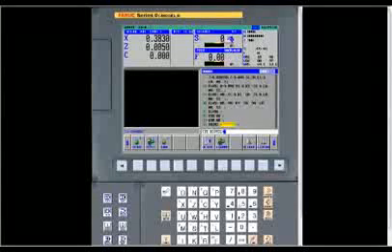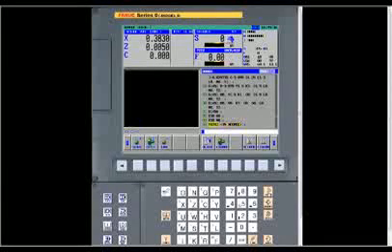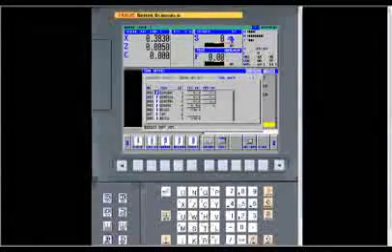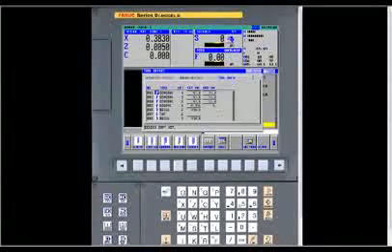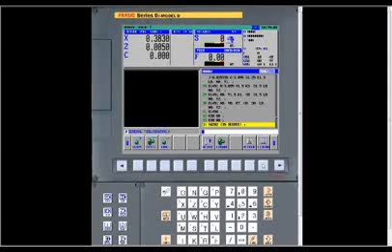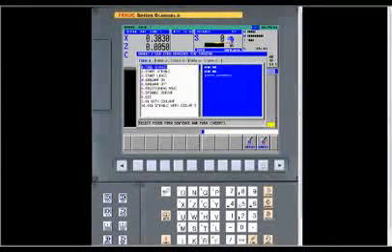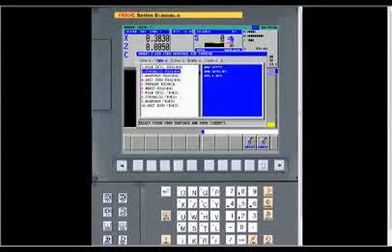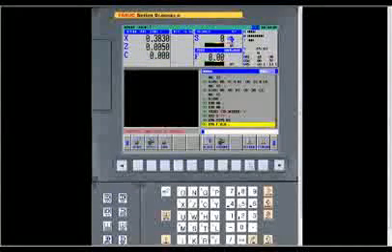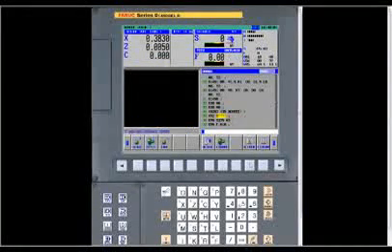And then we alter that, just like we did before. And again, if we highlight the entire line and press input, it takes us right into our tool data selection. So it's a general tool with a 35 degree tool. That's what I want. So at this point, what we want to do with that tool is go to fixed form. And again, we want to turn on our cut speed for pre-heat treated material. Insert that. Limit our RPM.